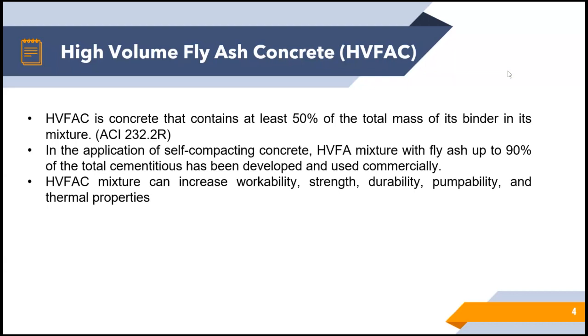So, what is high volume fly ash concrete? High volume fly ash concrete is concrete that contains at least 50% of the total mass of its cementitious material, referring to the standard of ACI 232.2R.